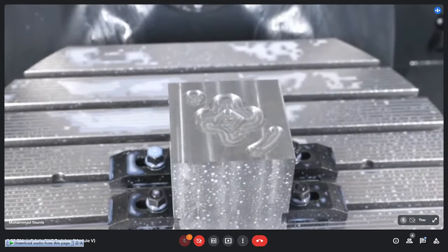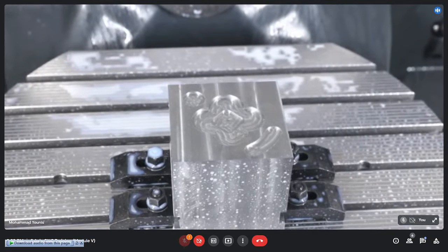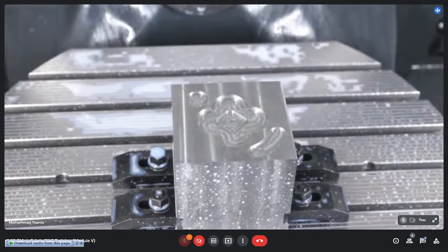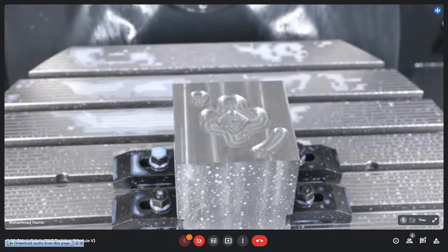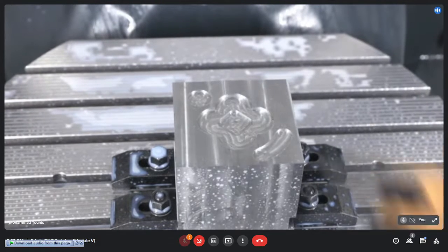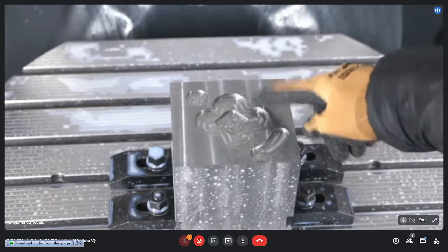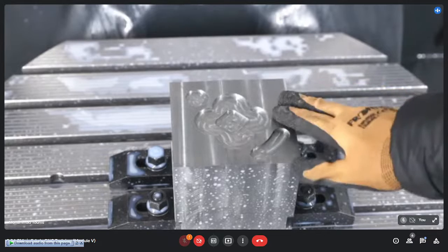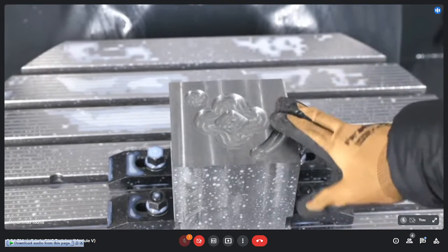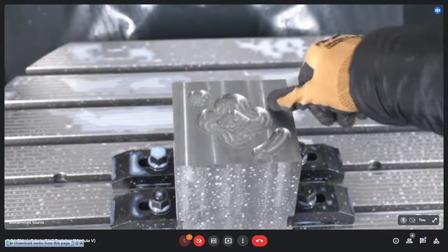But here on Siemens, on this 5-axis CNC, I have the option that I will just make the contour and tell the machine that I want to make a pocket milling, or I want to do a spigot milling. If I use a cycle of spigot milling added to this contour, then the material is removed from the outside of this contour. But here we have done this pocket milling. So we have got four pockets here.